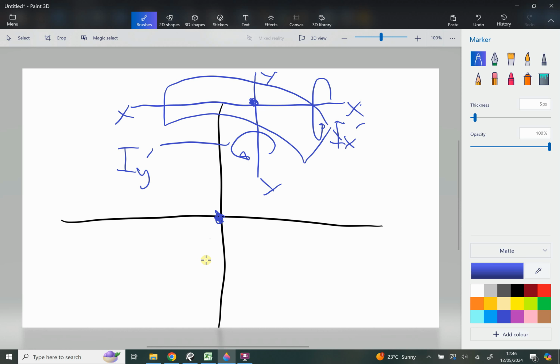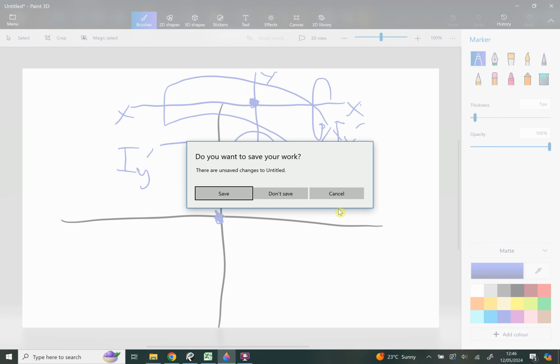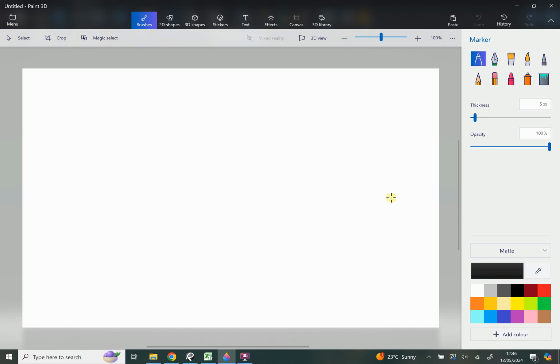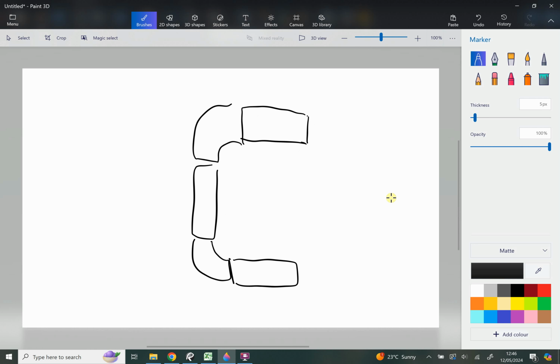And the reason this is done this way and derived this way is because if you know the I value about the centroid of the system, you can then use this to build up more complex geometry and work out the second moment of area for something like the channel section that you saw before. For the channel section, you would have something like rectangle, corner, rectangle, corner, rectangle. You'd get centroids of all of these. You'd work out your neutral axis, or your centroid of the whole system. The centroid of the whole system would be roughly around here, and then you'd basically do the parallel axis theorem again to work out the I value of the whole thing.